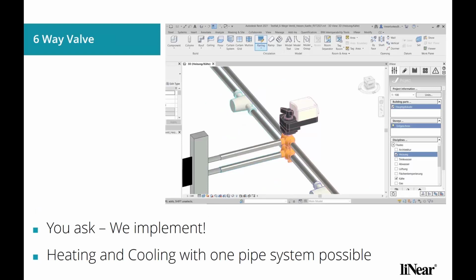Six-way valves are especially being used for ceiling heating and cooling systems. They enable various control setups for heating and cooling in one unit. Test results show that they have many benefits, such as lowering the pressure losses, and as a result, they give significant energy savings with pumps. That's why they are getting more and more popular worldwide.